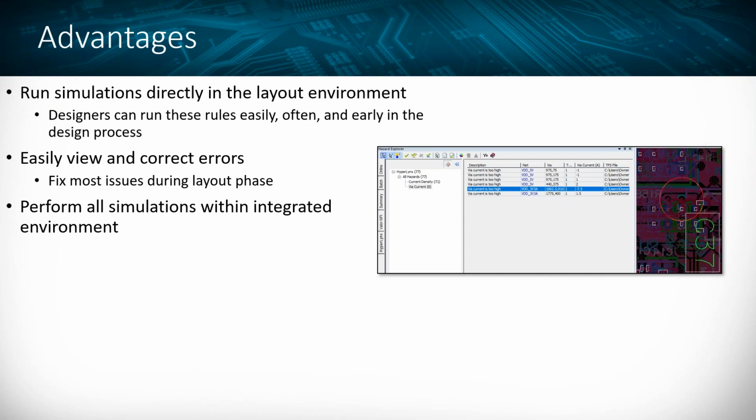Okay, so one major advantage of HyperLynx DRC in specific is that you can work together with your design review team to develop your constraints on what you want to check in these types of EMI checks. Okay, so the designer can actually just point to these rules that have been predefined with your company standards or perhaps a technology standard that you've developed, and then run those rules directly on the layout. So they don't have to be an EMI expert to run these types of rules.